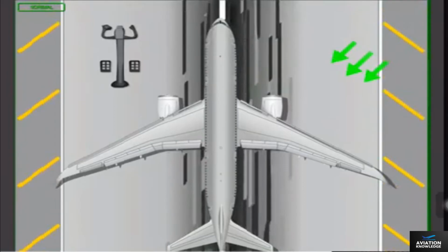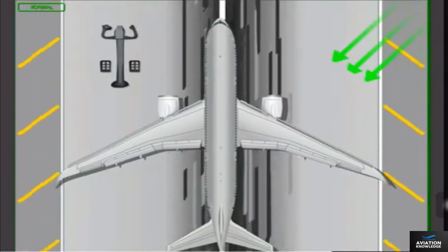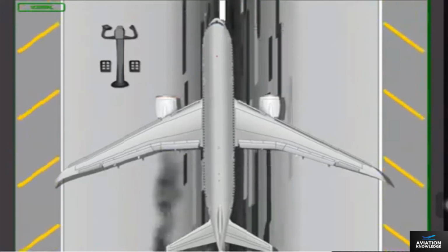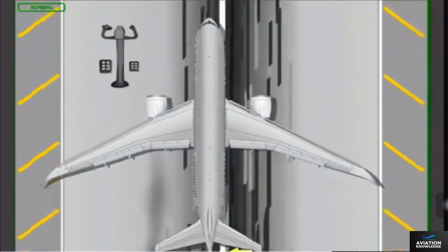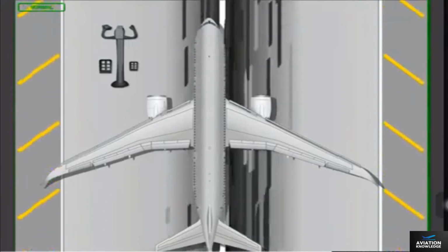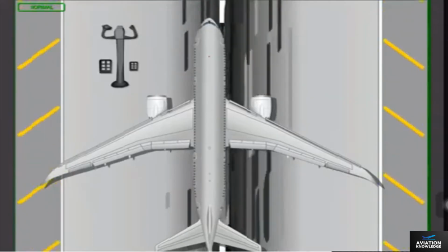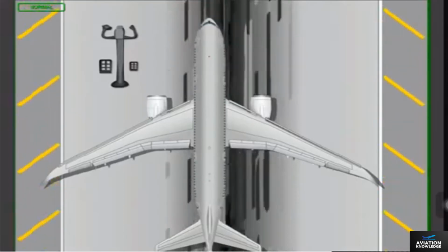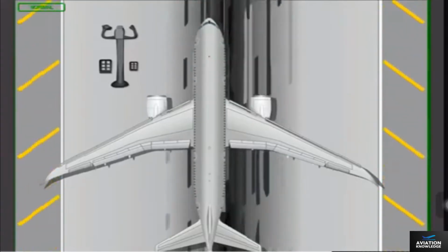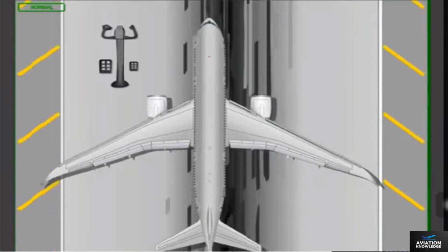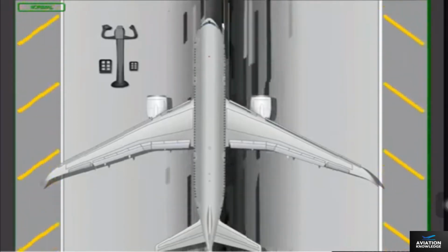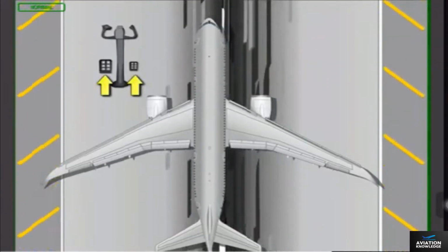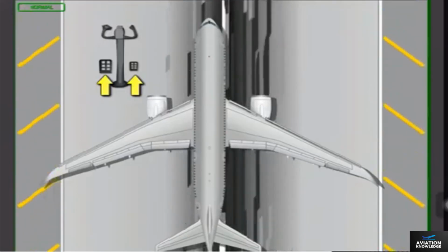On the ground above 60 knots ground speed, the flight control system attempts to maintain a yaw rate near zero by commanding rudder to counter the majority of the yawing moment due to an engine failure. The capability to counter a thrust asymmetry is an inherent part of the flight control system. The pilot can still recognize the initial onset of an engine failure through the airplane yaw cue, since the flight controls do not counter all of the yawing moment.